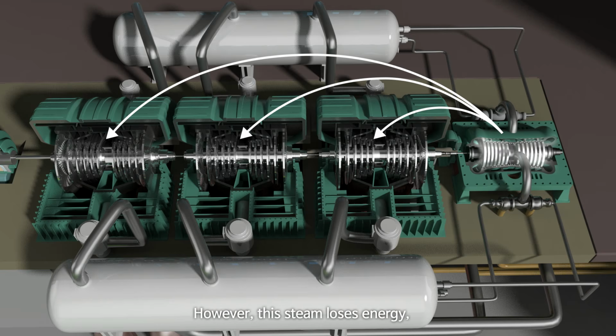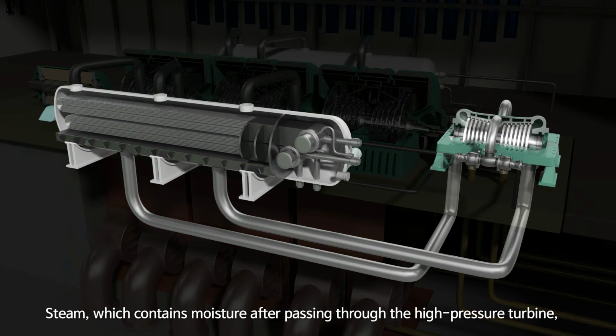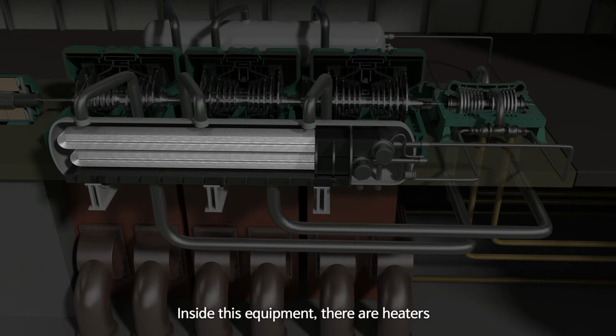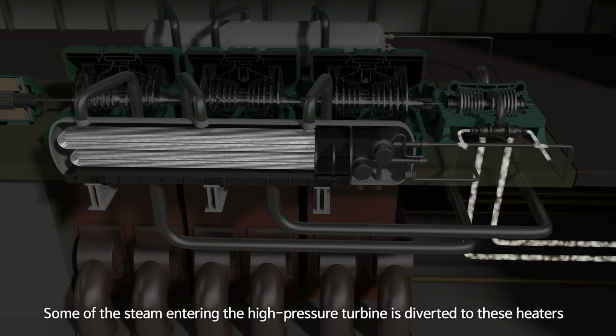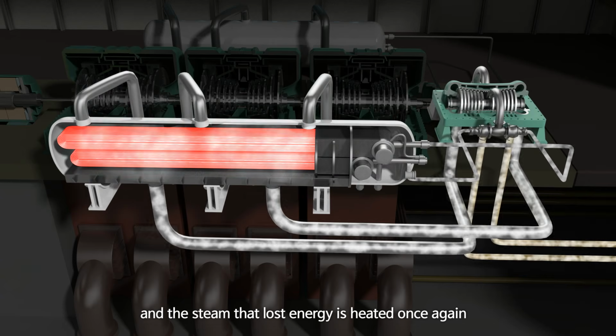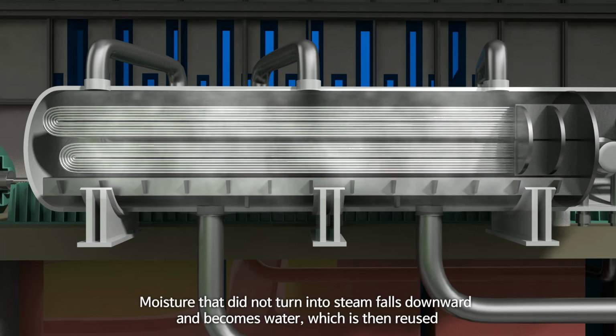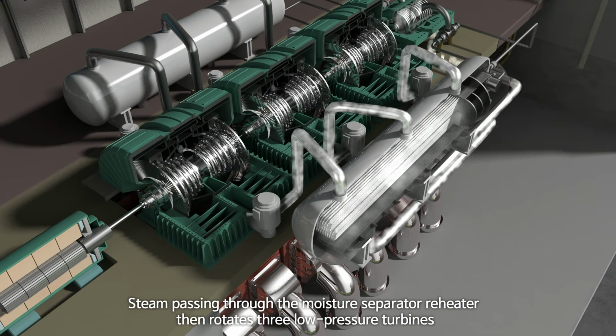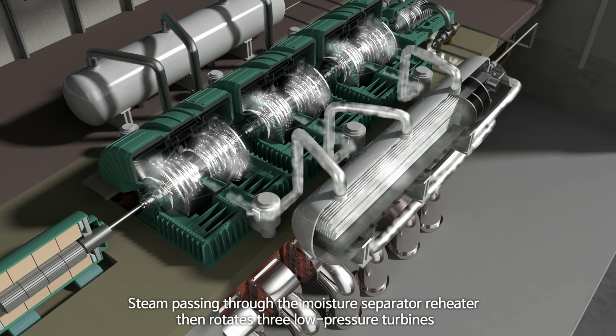However, as this steam loses energy, its temperature decreases and some of it becomes moisture. Steam, which contains moisture after passing through the high-pressure turbine, is sent to the moisture separator reheater. Inside this equipment, there are heaters. Some of the steam entering the high-pressure turbine is diverted to these heaters, and the steam that lost energy is heated once again. Moisture that did not turn into steam falls downward and becomes water, which is then reused. Steam passing through the moisture separator reheater then rotates 3 low-pressure turbines.